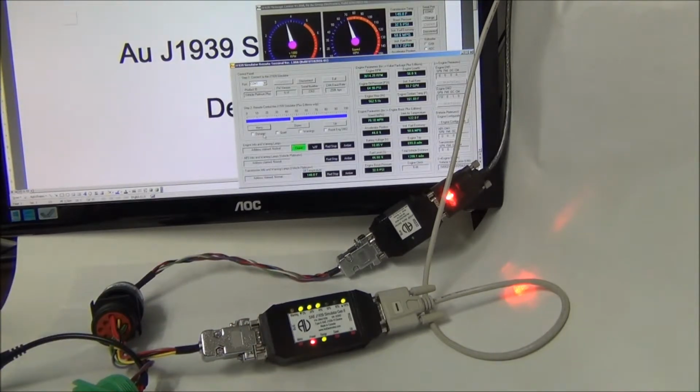Over here, there is a dynamic checkbox. If you check this dynamic checkbox, without touching the device or the remote terminal GUI, the simulated value will go through the cycle automatically. Uncheck it, and the value will automatically return to the previous setting.